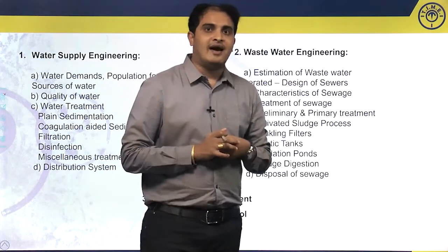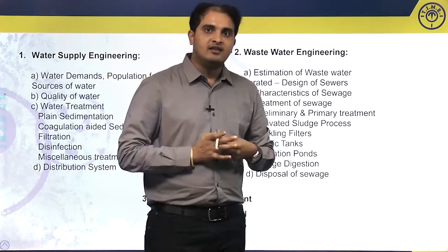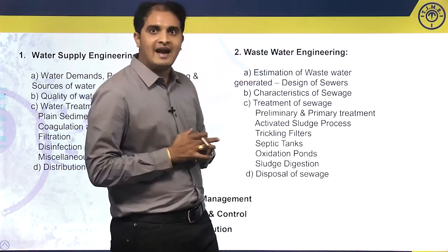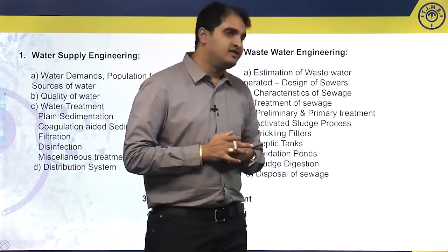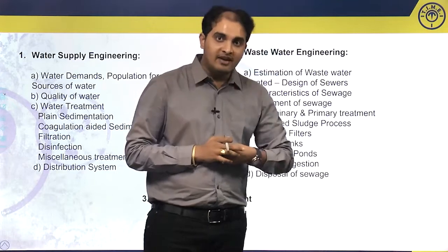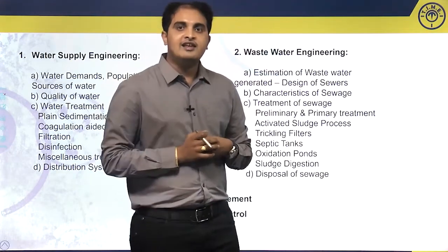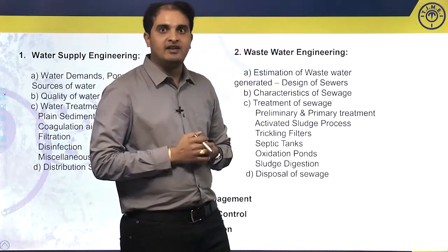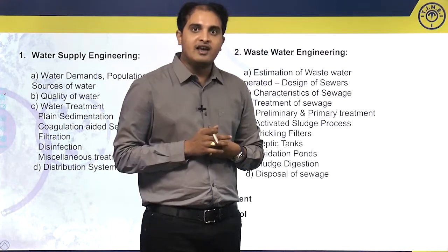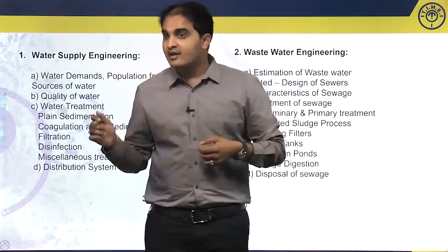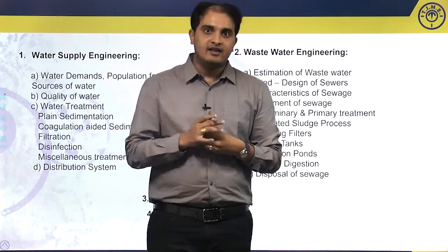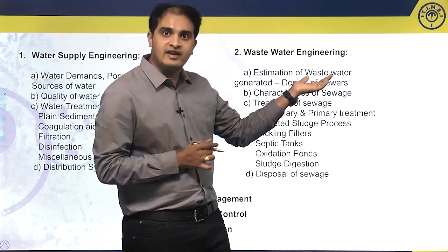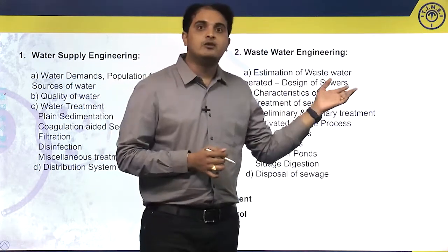BOD means biological oxygen demand. That means the amount of oxygen that is required by the microorganisms in order to decompose the organic matter. Generally in sewage we have microorganisms present and we also have organic matter present. Here the organic matter is very dangerous. In water supply engineering, we consider the microorganisms as our enemies. Here we need to consider the microorganisms as our friends, because they are going to decompose the organic matter.